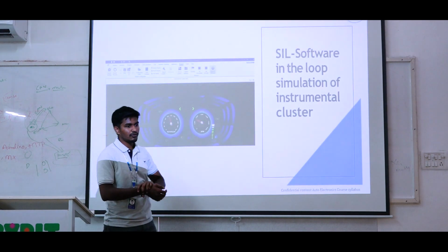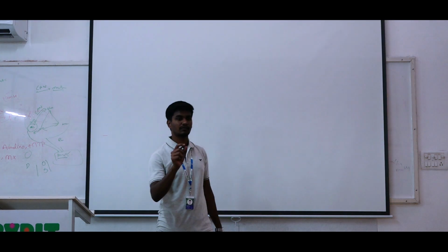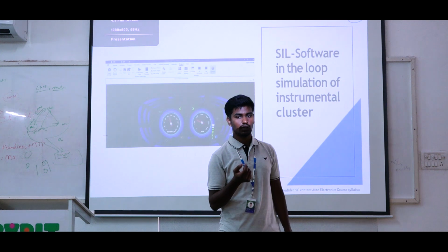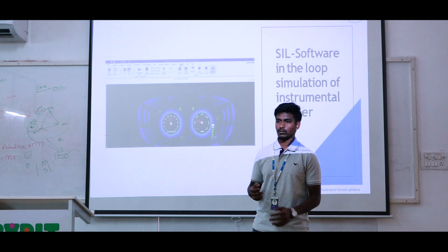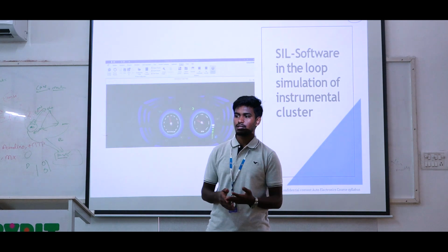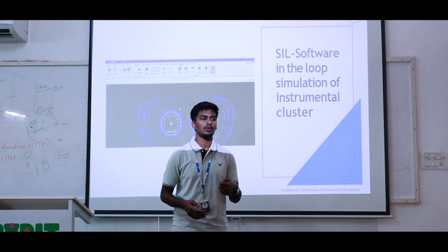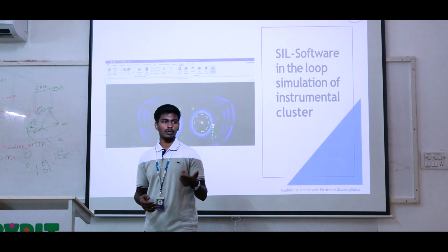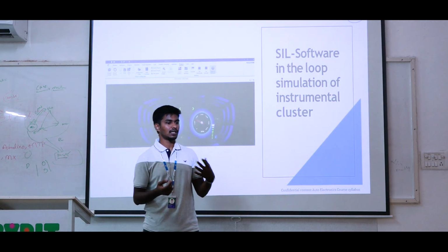It is called software in the loop simulation of the instrument cluster. It is called SIL. It is one of the attractive keywords for recruiters also. We can mention it as SIL or as software in the loop simulation. Another simulation is hardware in the loop simulation. One more is model based simulation, or model in the loop simulation. SIL, MIL, HIL. For MIL we need the assistance of MATLAB.